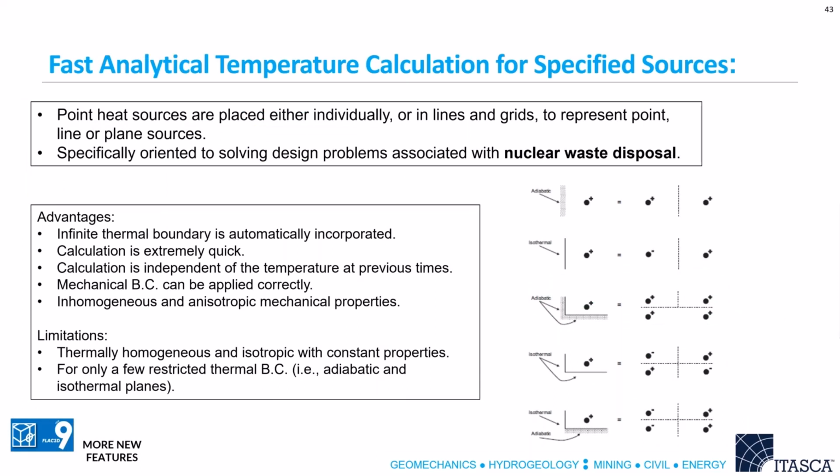And then the last feature I'm going to talk about is maybe not for everybody, but it's certainly useful if you're doing these nuclear waste type of studies. It's something we took from 3DEC and put into FLAC3D, and it's the fast analytical temperature calculation for specified sources. If you can assume that your material is infinite in extent and isotropic, you can calculate the temperature at any given time for any given set of sources analytically.